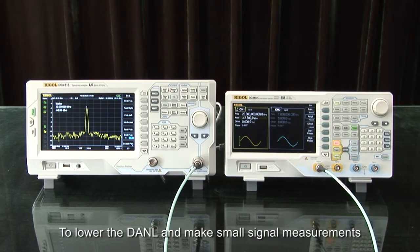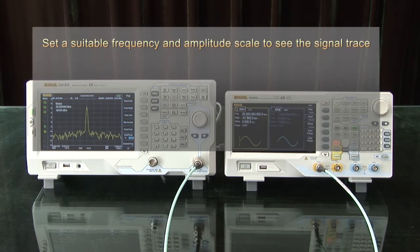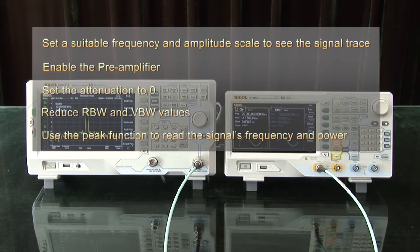To lower the DANL and make small signal measurements, we want to set a suitable frequency and amplitude scale to see the signal trace. We want to enable the preamplifier. We want to set the attenuation to 0 dB, reduce the resolution bandwidth and video bandwidth values, and use the peak function to read the signal frequency and power.